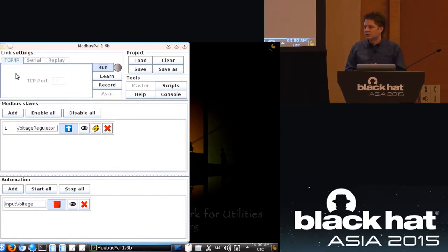Now what we need to do is have some tool to communicate with it. We need a tool to be able to generate Modbus traffic. Modbus literally is so simple, you can open up a text editor, type the hexadecimal values that you want inside of that packet like we showed you in the previous screen, and pipe that into Netcat. And you literally can speak Modbus with Netcat. That's how easy the protocol is. But instead, we're going to use a dedicated Modbus client to talk to the protocol.